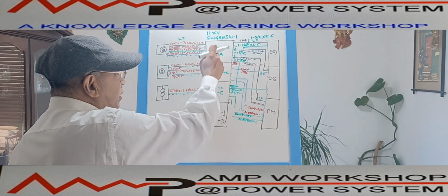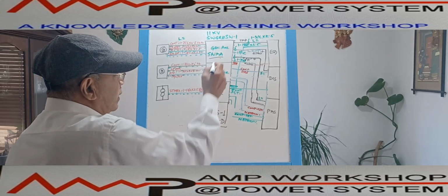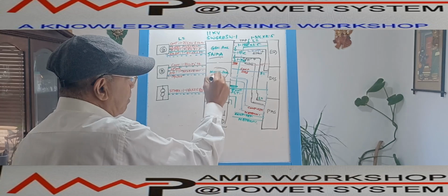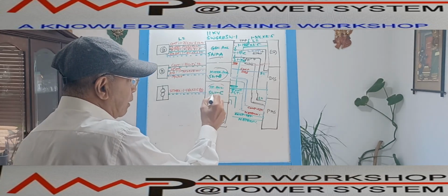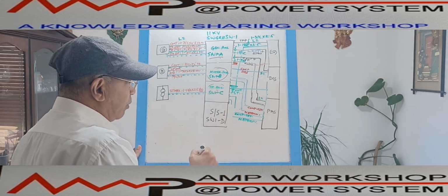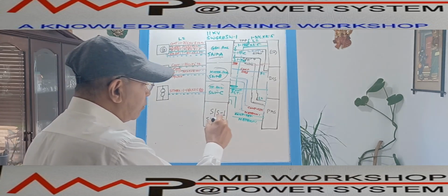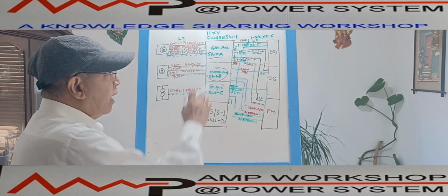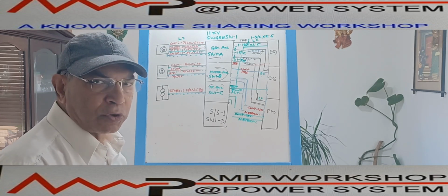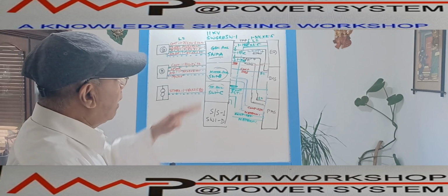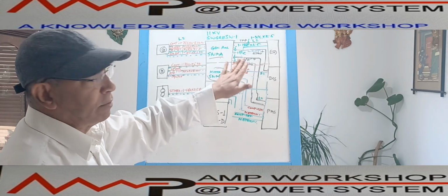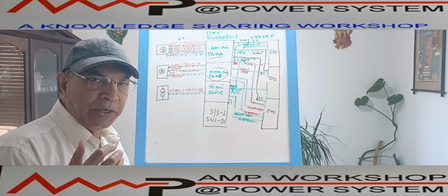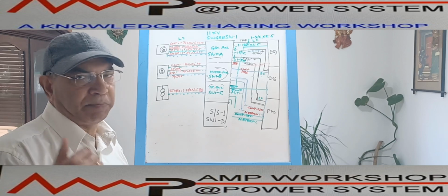It will be copied the same for multiple generators. The same type of generator switchgear panel A, a generator panel, will be copied. For the motor panel, the same type of arrangement will be copied. For the transformer panel, whatever the arrangement, the same will be copied. Similarly, for other substations also, the same thing will be copied. That's why, for typical analysis and clarity of the drawing, I have shown four typical 11 kV switchgear panels, and how these panels are connected with the various field equipment, considering control, indication and metering purposes only.